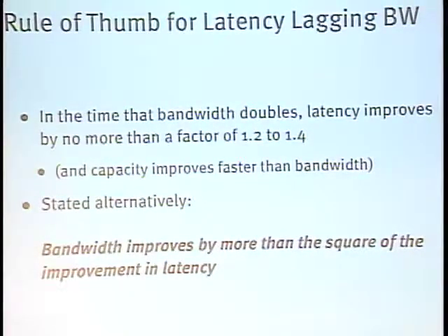So the question is, I think it would depend on what the physical limit was, whether it would stop latency in its tracks. If we can't make these chips any bigger, if we reach this fundamental limit on size, well, that sort of caps latency because you only have so far to go. But if we can't fit any more pins around the outside, that's a different thing. That might cap bandwidth because we can't send more data off. So we'd have to have specific physical limits. The good news is we're not really there. We have more room to run. So we haven't hit a physical limit yet.